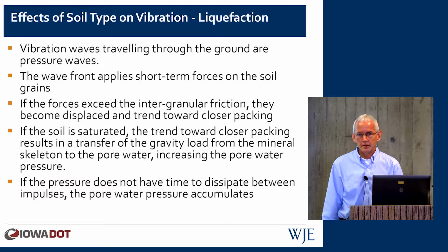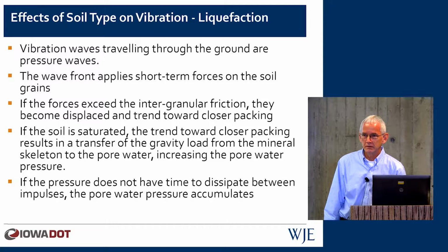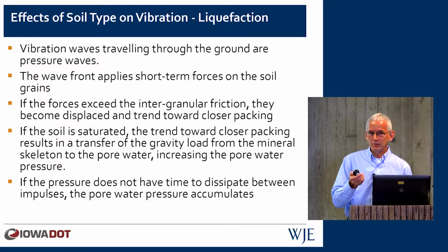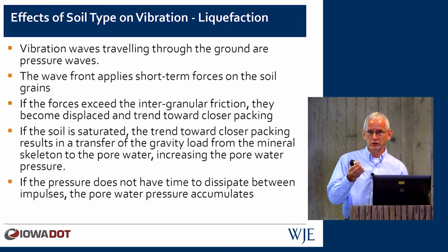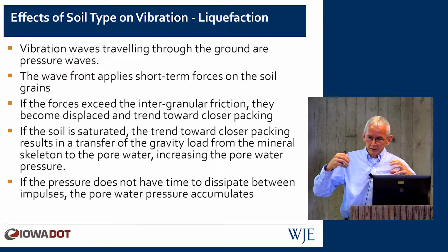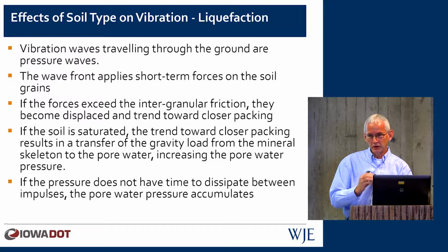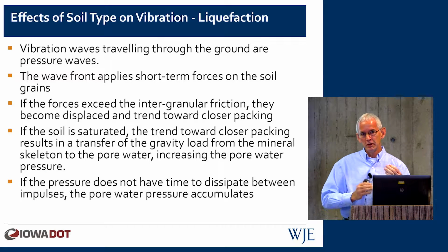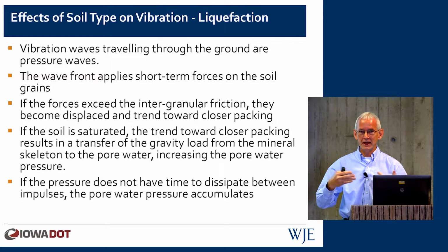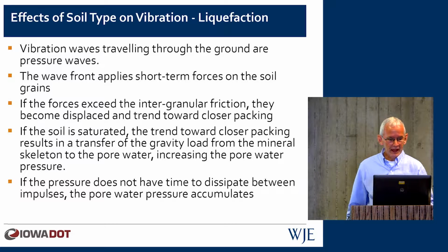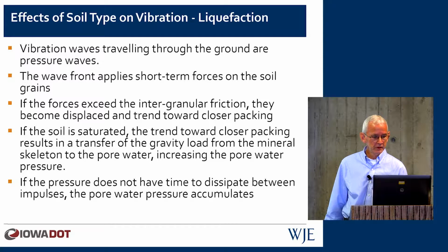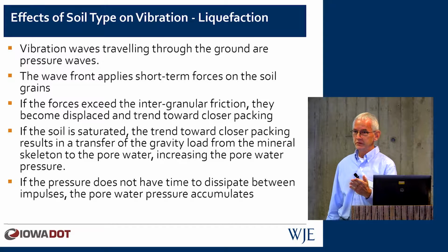That pore pressure can dissipate with time. But in the process of developing that pore pressure, at the instant when the pore pressure goes up, you tend to be pushing the grains apart. They're already confined, pushing against each other, and you develop a pressure that's pushing them apart. You can develop a large enough pressure that actually disperses the grains so they're not touching each other anymore. And that can happen if the pressure doesn't have time to dissipate between impulses, the pore water pressure accumulates.